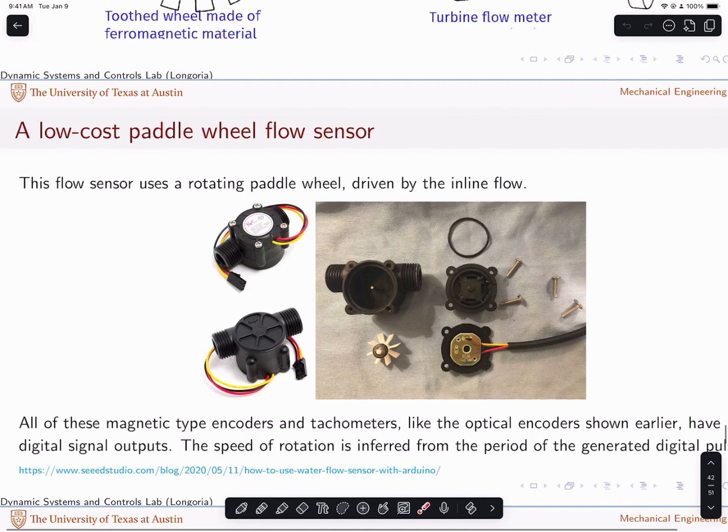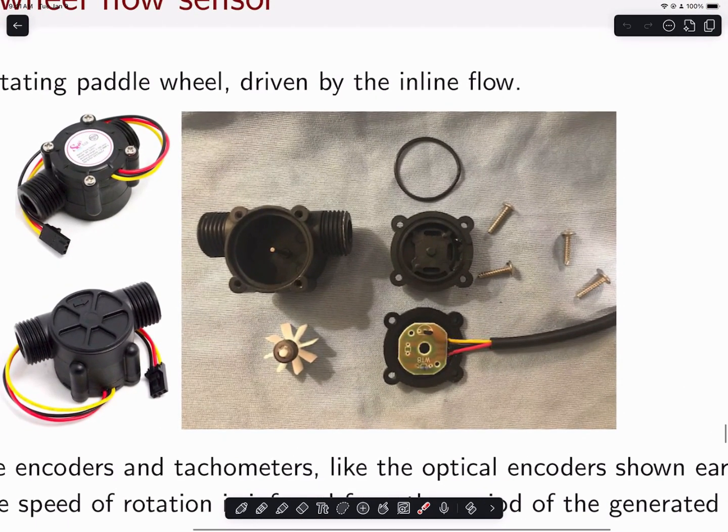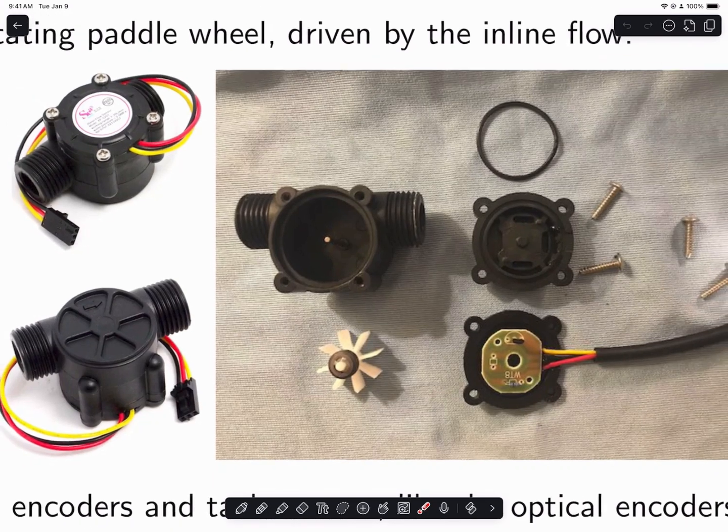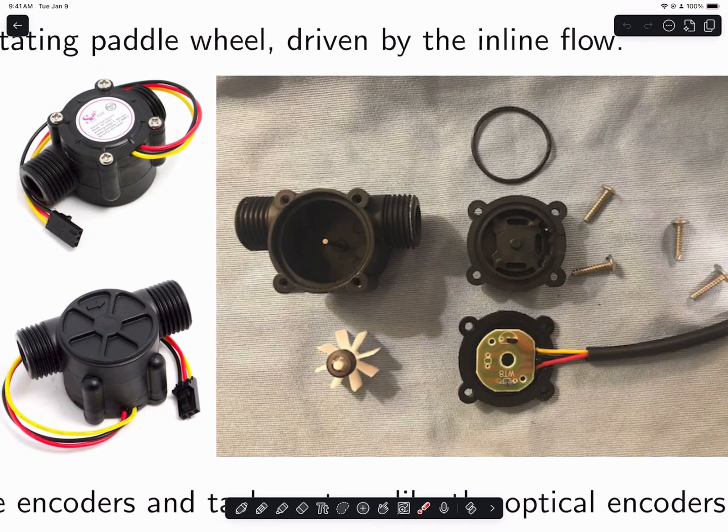And actually you see this in some really low cost flow sensors. These are little turbine type flow sensors that are really neat. Here's the turbine, and I believe this part right here has the magnetic pole pieces, and again, it has a magnetic Hall effect sensor that can pick up the rotational rate, and in that way, given the number of vanes, you have a flow sensor, right?